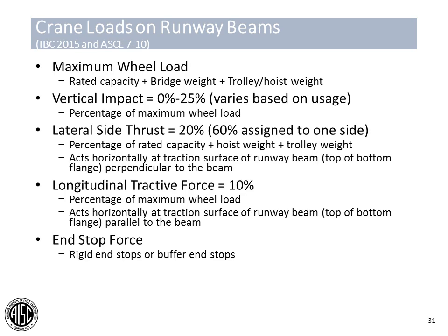The loads that we need to specifically design the runway systems for include a maximum wheel load. This may be provided by the crane manufacturer, or if you need to calculate it, the way that you would calculate it would be take the bridge weight and evenly distribute that bridge weight to your end trucks and each of the wheels within the end truck. Then you would take the rated capacity of the hoist and trolley assembly, as well as the hoist and trolley assembly itself, locate that near one of your end trucks, and distribute that force to the total wheels on one end truck, and that will give you your maximum wheel load.